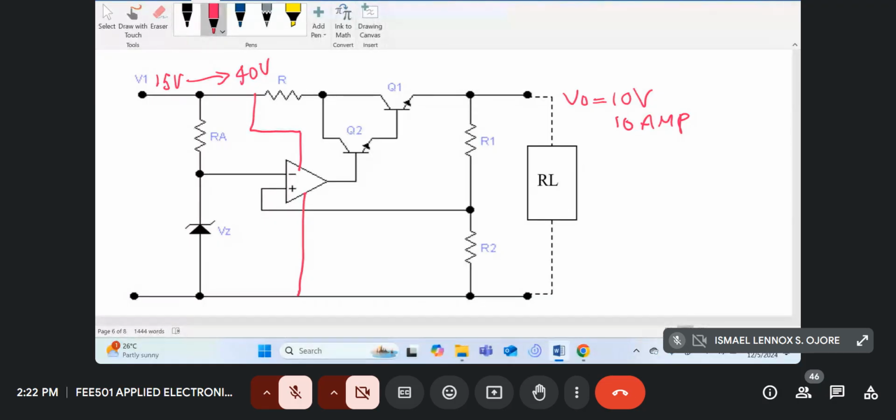So the peak voltage between the positive VCC and minus VCC is 18 times 2, which is 36 volts. So for example, in this problem, where the input voltage can go up to 40 volts, it's going to destroy the op-amp. You have to get an op-amp which can handle that 40 volts. Okay, 40 volts means minus 20 to plus 20.